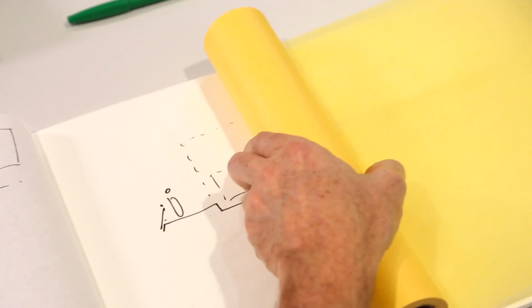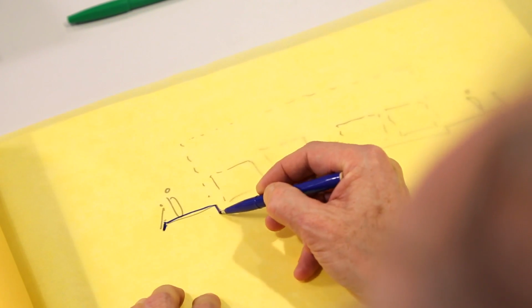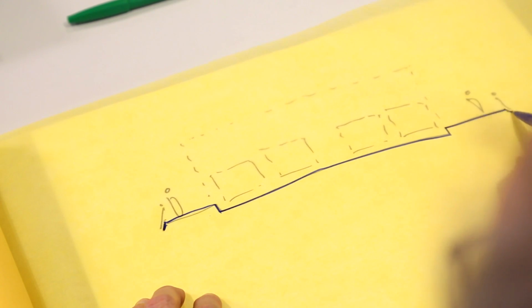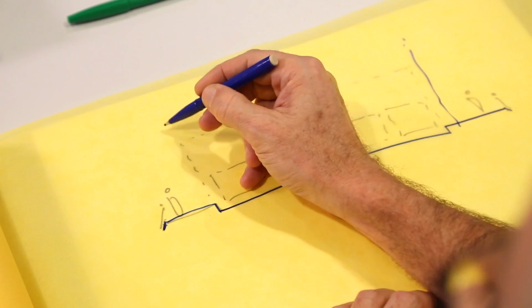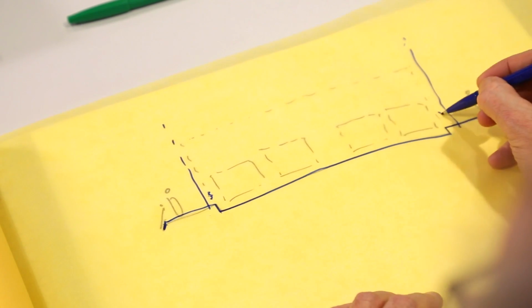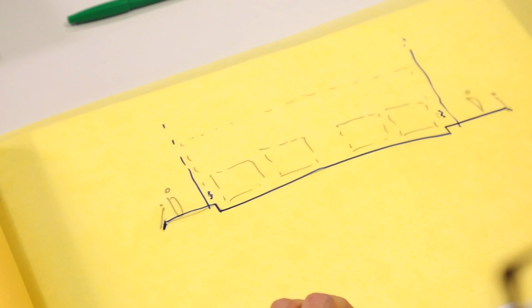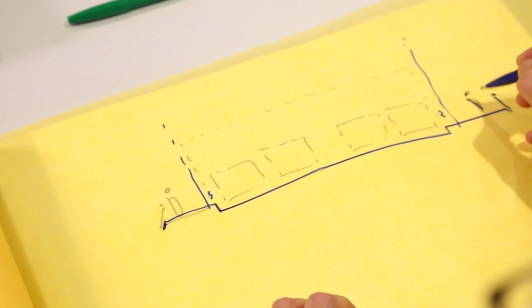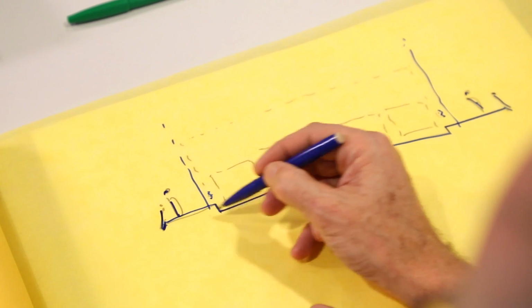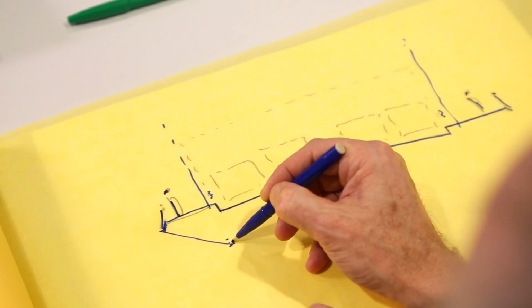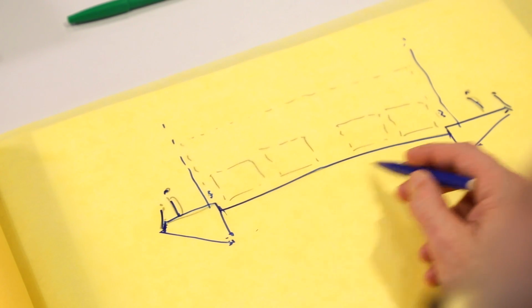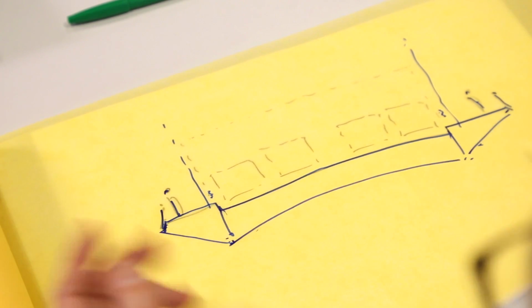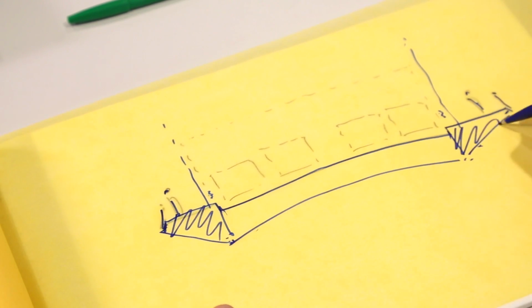Another way of doing it would be to have structure down each side. That is why I say you need to be thinking of both the cross-section and the long section at the same time. You could imagine a cable-stayed solution, for example, with stays either side of the roadway. Obviously you have crash barriers and things, as indeed we would have had safety barriers either side of the stays in the other solution as well. But if those could be stays, then our girder is here. I don't know what sort of shape this might be, but maybe you've got some sort of girder at each edge, and now this doesn't need to span so far. We could do something unusual with it, and so this is our longitudinal element.